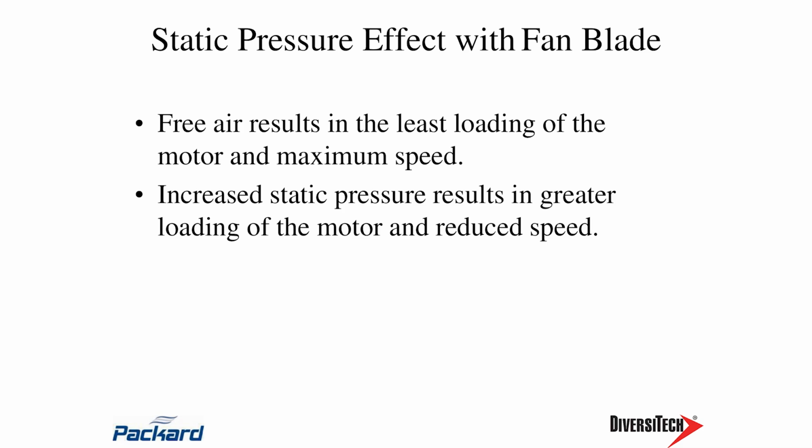What would be free air? If I were operating a motor with a fan blade on it, and if I'm running it on this table here, this is considered free air. That would be the least load on that motor. But now as I add static pressure, how would I add static pressure to that? Put it in my condensing unit. What if I put it in the condensing unit but don't put the guard on top of it? Have I added static pressure to that? Yeah. What if I put the guard on it now? Does that change the amount of static pressure I've applied to that?